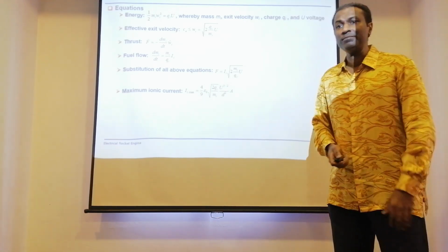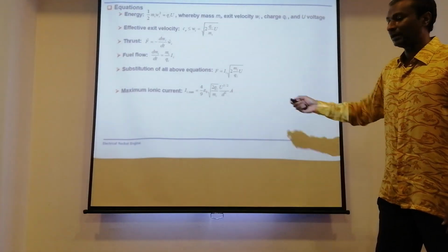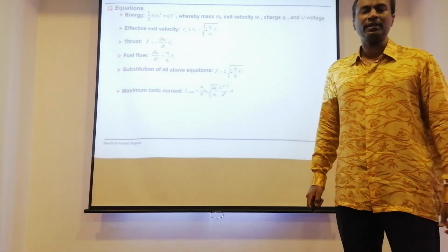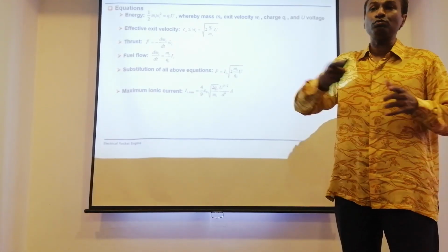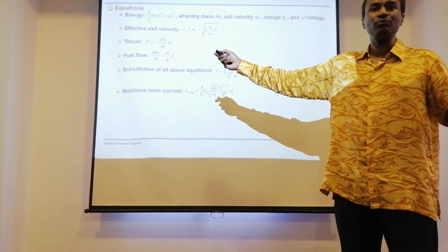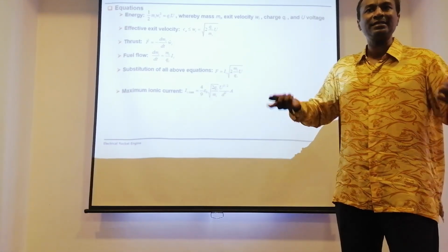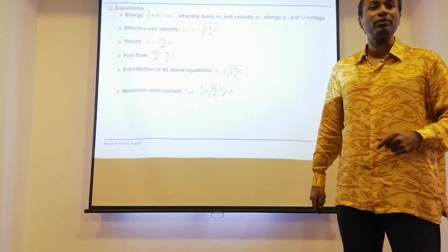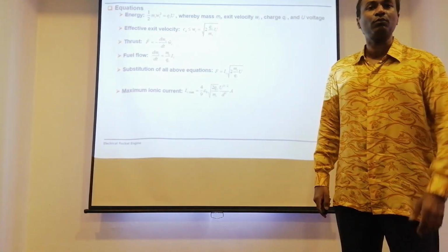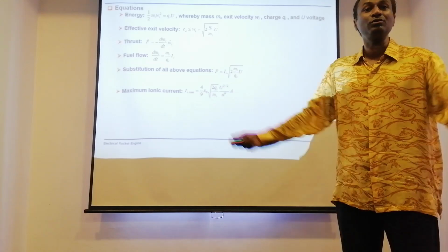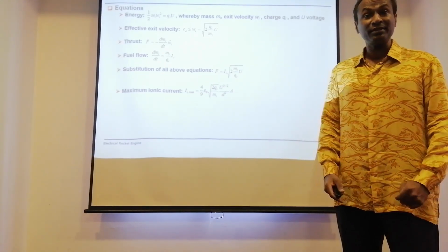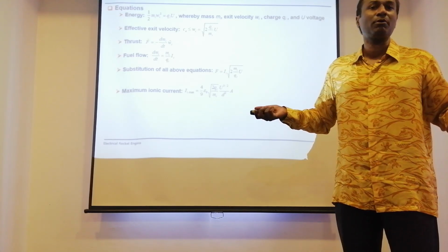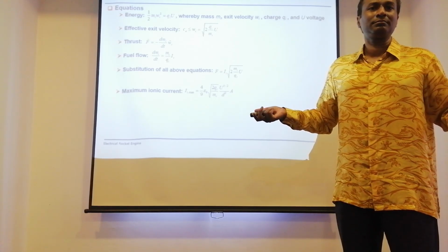Now, another problem is this. When the electric current, we set it at maybe about 3 amperes. If you want the actual power that you need, the only way to deliver that is to increase the voltage. That is the reason in these systems the voltage can be in the thousands of volts, 1000 volts. Whereas in a satellite, even in a space station, the bus voltage is about 150, 160 volts. It's not much.